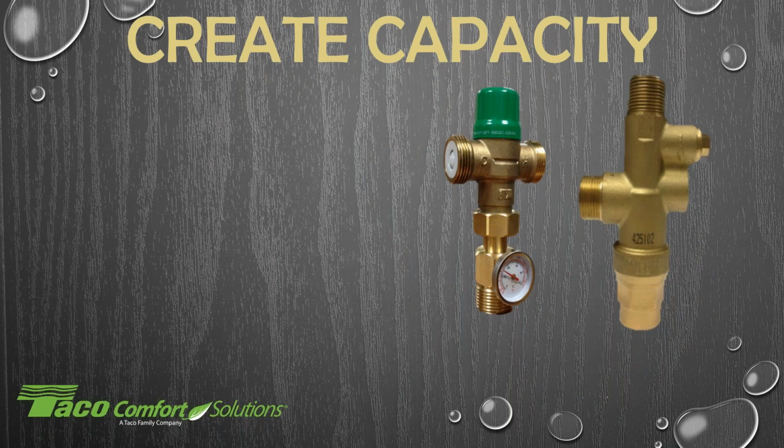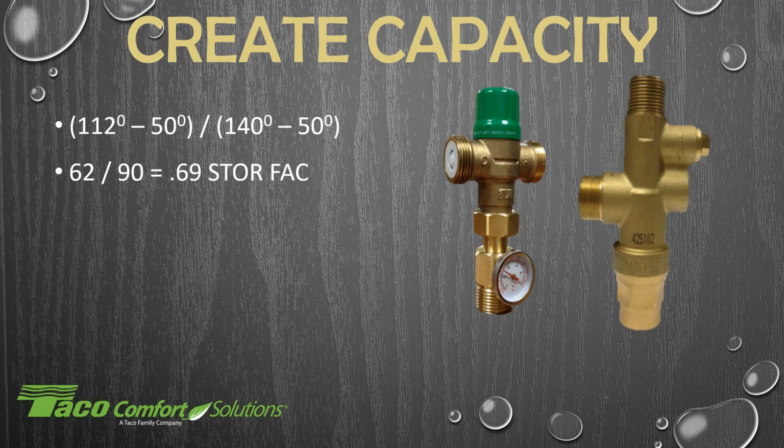So let's create that capacity. Let's take a look at how you would use this formula. For example, we have 112-degree delivery going out to our house. We have 50 degrees coming in from the street or your well. We're going to store at 140 degrees in our tank, minus the 50 degrees coming in from the street. We math that out, and we get 62 divided by 90, which gets us a 0.69 storage factor.